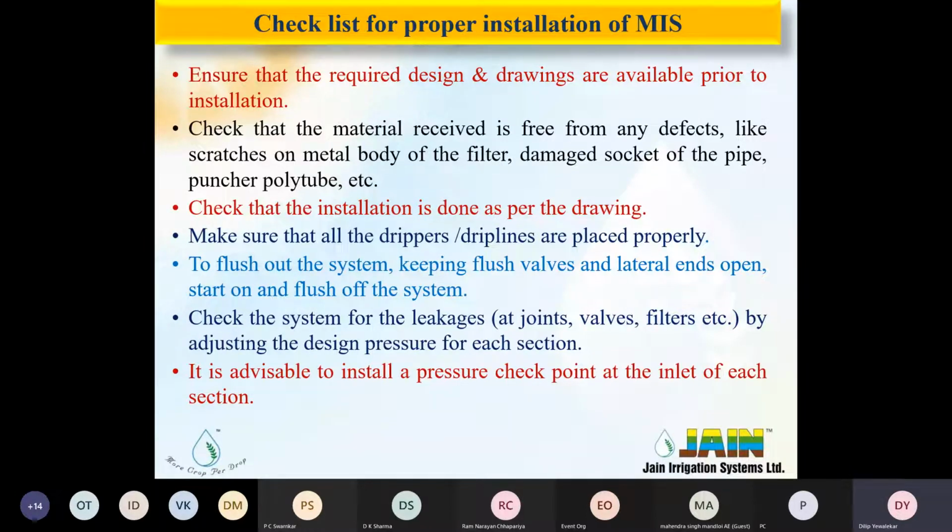That means check whatever material is required to complete the installation. After that, check the field and check the drawing, whether it matches, or if some difference or adjustment has to be made. Then contact the design engineer to make any addition or changes in the system.